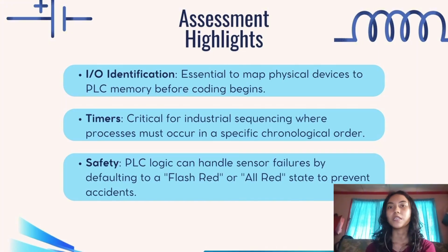Lastly, safety is always a priority in PLC programming. If a sensor fails or a problem occurs, the system can be designed to default to a flash red or all red state. This helps prevent accidents and keeps both drivers and pedestrians safe. Overall, this project helped us understand how PLC logic supports reliable and fail-safe control systems.